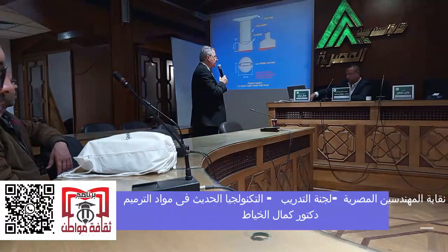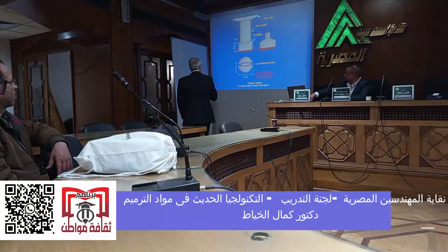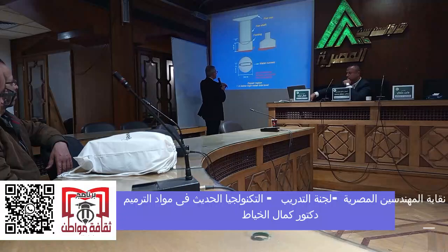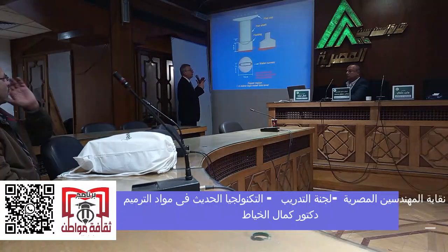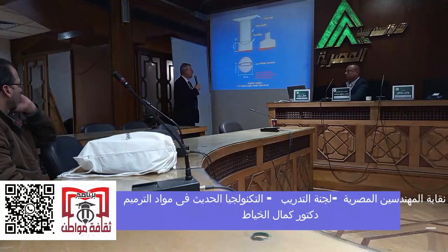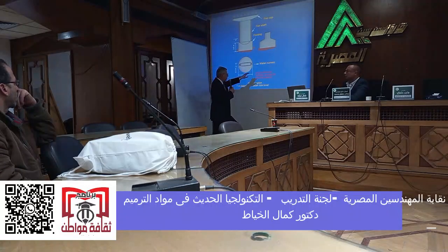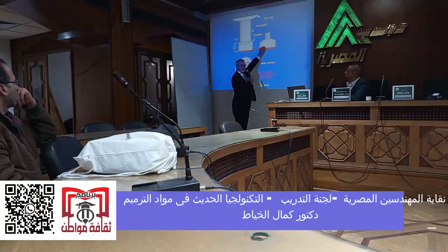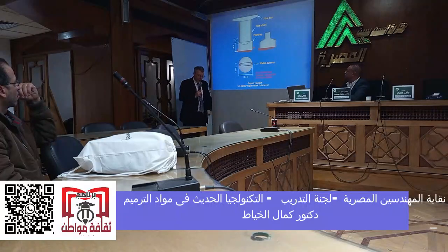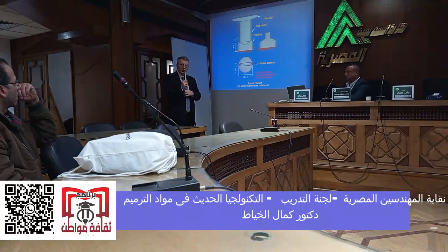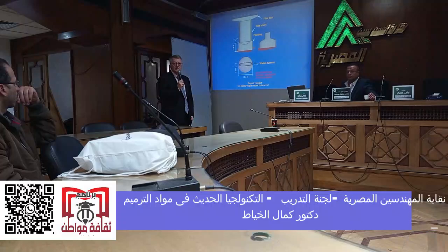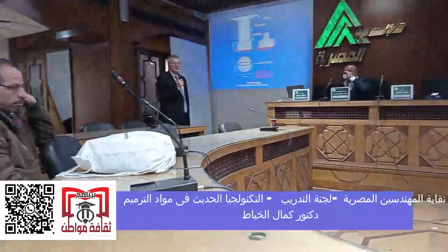So when this bridge was constructed, you have the pier that is properly reinforced, and the footing is sitting on soil and it looks like a bell shape. It's totally unreinforced, so there's no reinforcement here. It's unreinforced concrete. There's only reinforcement at the bottom to spread the load. This was cast during the summer, mass concrete, and it cracked. They did not control the temperature. Next.